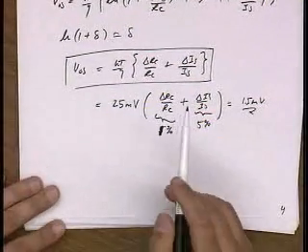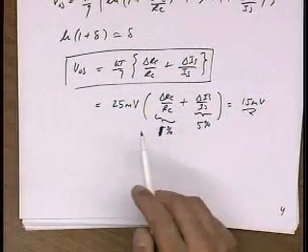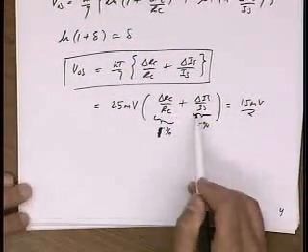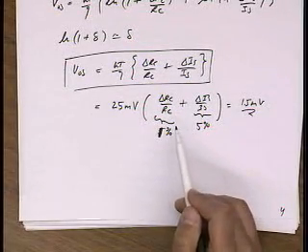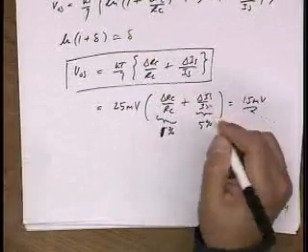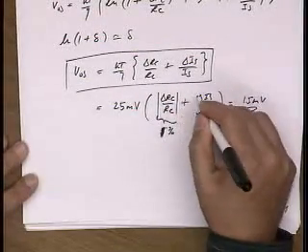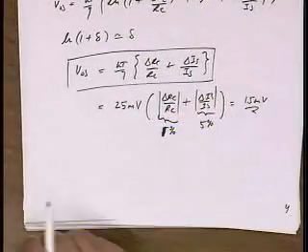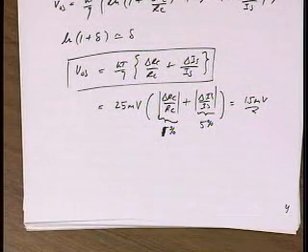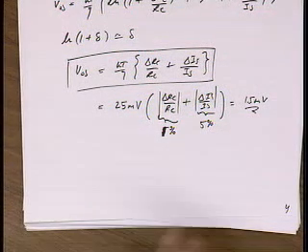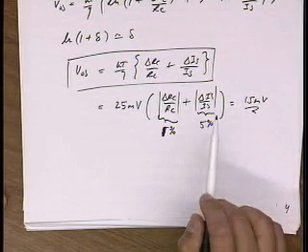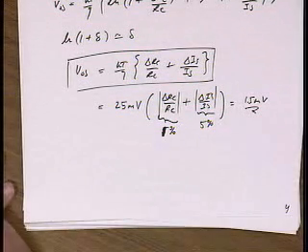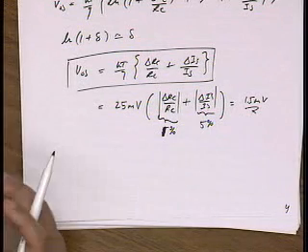Now here, I just assumed that these things add together, right? I could have gotten lucky and had subtraction, in which case I would have had 1 millivolt, right? So usually what we do is we assume, let's say I want to know a typical number. As a good engineer, I'm pessimistic, and I assume the worst case. So this will give me a bound on the error. But remember that this number is kind of meaningless. It doesn't mean that you're going to go out and measure every amplifier and you're going to get 1.5 millivolts, right? It could be negative, it could be positive, it could be 0.7, it could be 1.